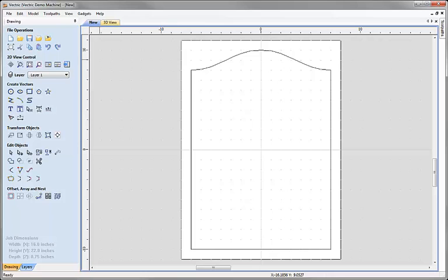So I know when I machine the outside shape of my raised panel that I'm going to use a specialist cutter, and that has a cutting width of 1 3/8 of an inch, and I have that information from the manufacturer of the cutter. So I'm going to take my outside vector and offset it inwards by that distance, so I know where the edge of my OG shape is going to be around the panel. That'll also be a vector that I'll be able to use when I come to machine the part, so I can profile around it.